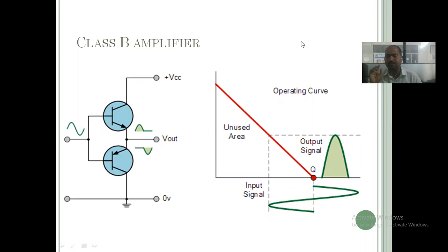So we design another amplifier which solves the burden of 360-degree working of the transistor. We use two transistors working in alternating 180-degree half cycles, so there is no burden on either transistor. That's why the working level of the class B amplifier improves.